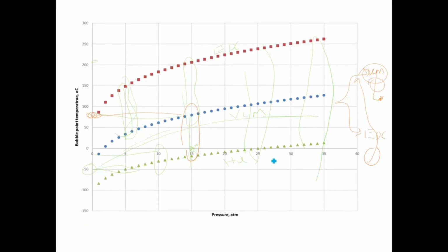So what we have here, if you put the pressure at 5 bar, 5 atmosphere, you can clearly see that your vinyl chloride monomer boils at roughly 40 degrees centigrade, whereas the ethylene dichloride bubble point temperature is almost near 80 degrees centigrade.